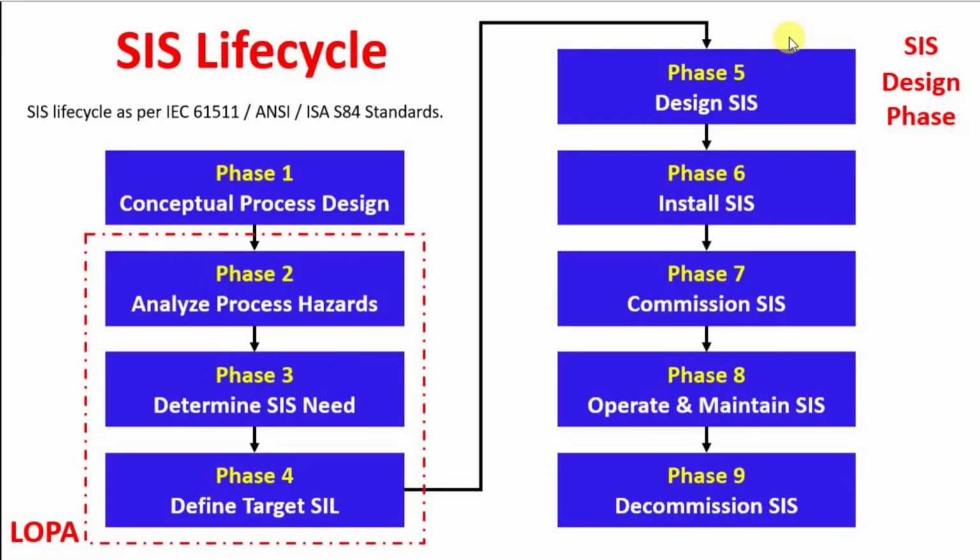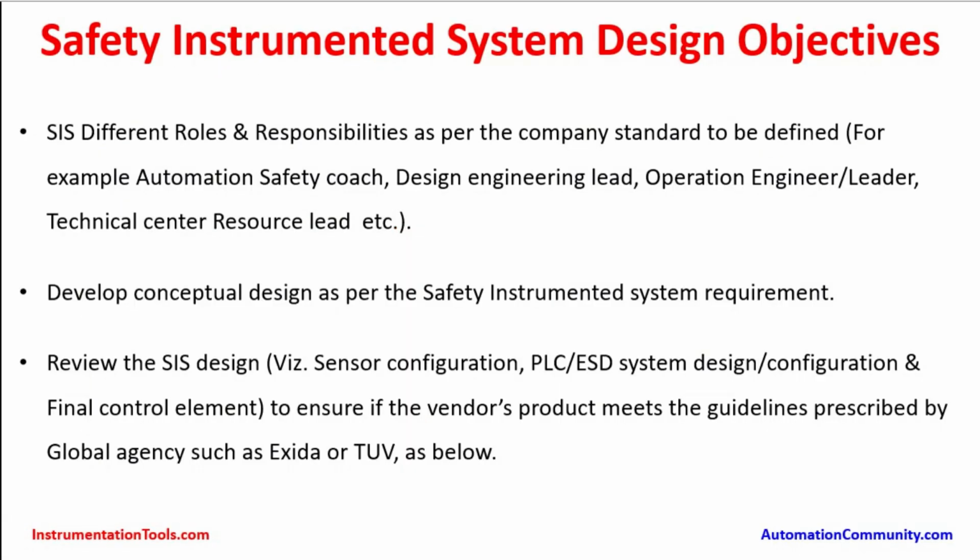All this, what is to be installed and what is the type of configuration, all these things have to be ensured. To ensure this, review the design, like the sensor, logic solver, and final element, to ensure the vendor's product meets the guidelines prescribed by global agencies such as exida or TUV.